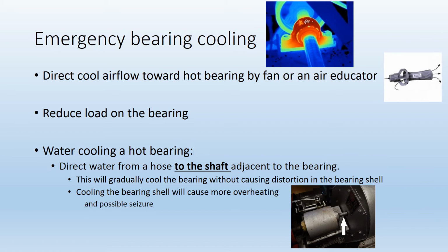Another option, if it's available to you, is to reduce the loading on the bearing. That will reduce the amount of heat going in. Another thing is to water cool the bearing, and be very careful when you are doing water cooling. You'll take a cold or a cool water and direct the water onto the shaft beside the bearing. Never put the water directly on the bearing.